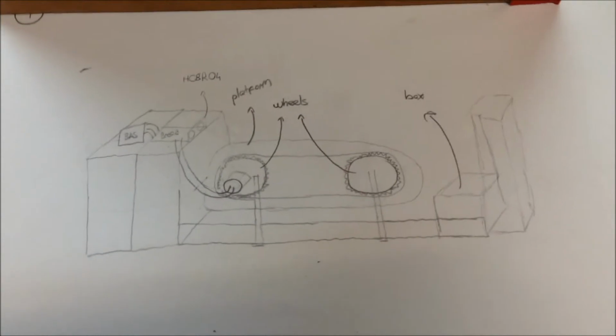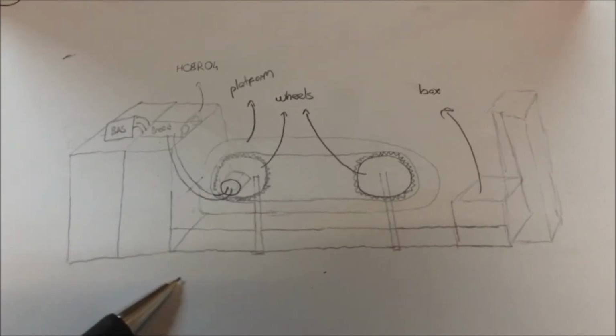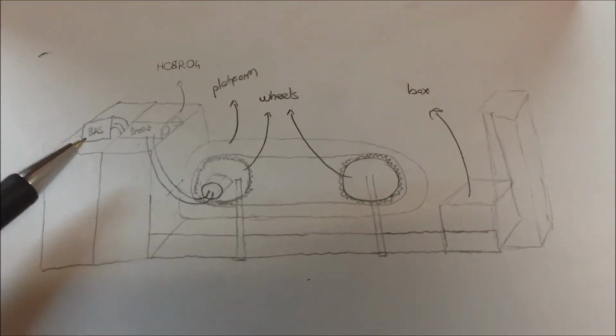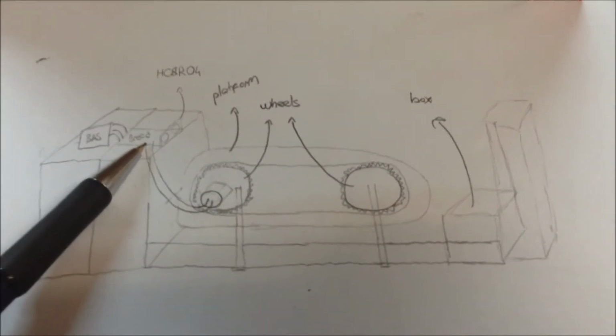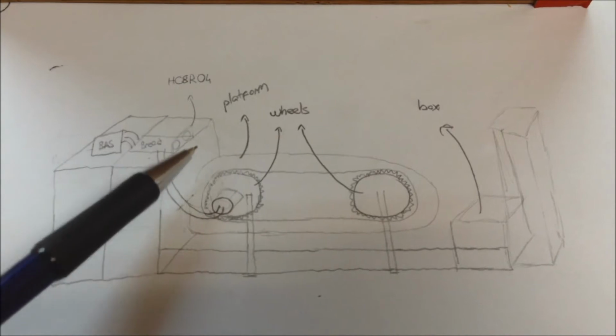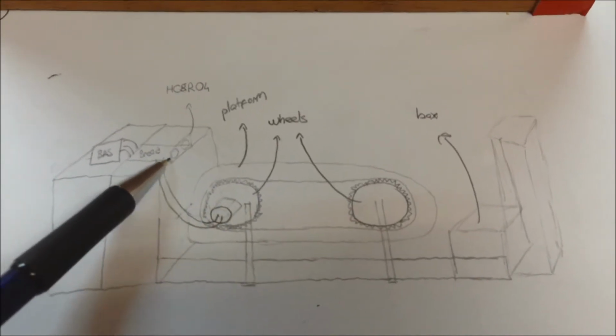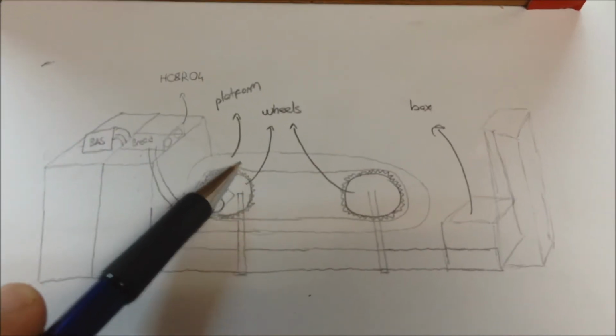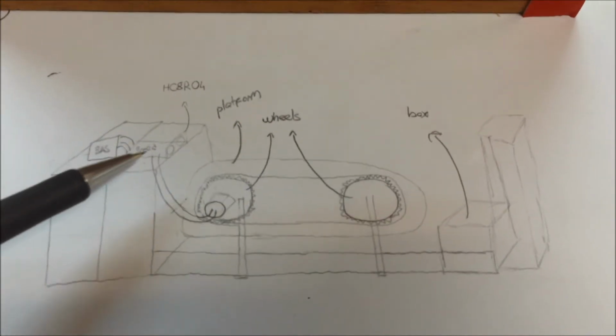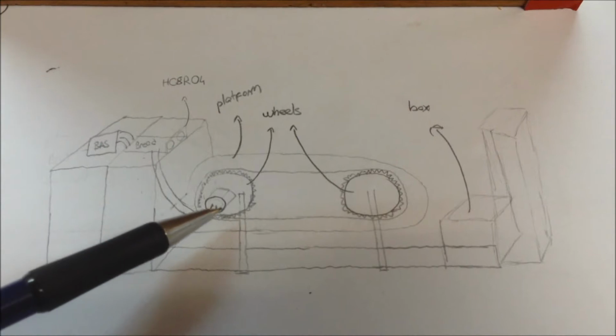And the project demo has a design just like this. We have a Basys 3 here, and the Basys 3 is connected to the circuit design on the breadboard, and there is a proximity sensor on this breadboard which is directly parallel to the platform of the treadmill, and the circuit is connected to the DC geared motor here.